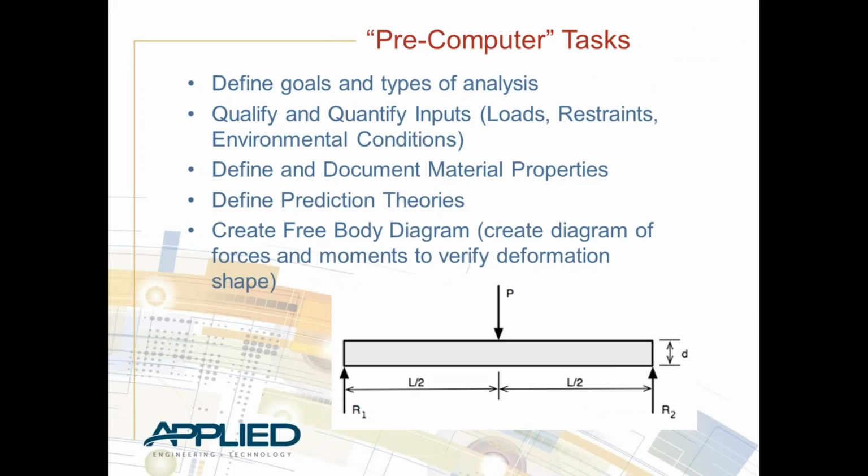Okay, now maybe we figured out it's a linear thing and we think, okay, we can do this in an Inventor simulation. Maybe it's more of a simple issue, or even if it's fairly complex, you can still do both static and dynamic types of analysis within Inventor Professional. So there's a lot of capabilities there. But even before we start diving into it, maybe we've got our model designed, don't just jump into it and start adding your forces and constraints and whatever it might be. Definitely take a few minutes if possible to kind of plan out: okay, what am I looking to find here? What are my goals of this analysis, and what type of analysis am I doing here? Is it buckling?